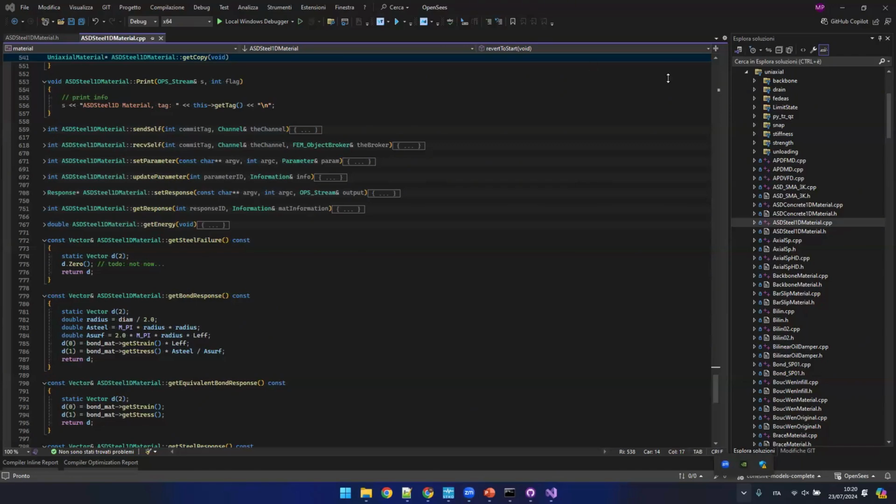Okay, so I was expecting this because compiling C++ is not easy. But this is the way if you want, you go into OpenSees and you put new stuff. It's convenient because you can do several things from TCL and Python, but if you really want to add the new capability to OpenSees, you need to code it, and you cannot do it through Python. Okay.